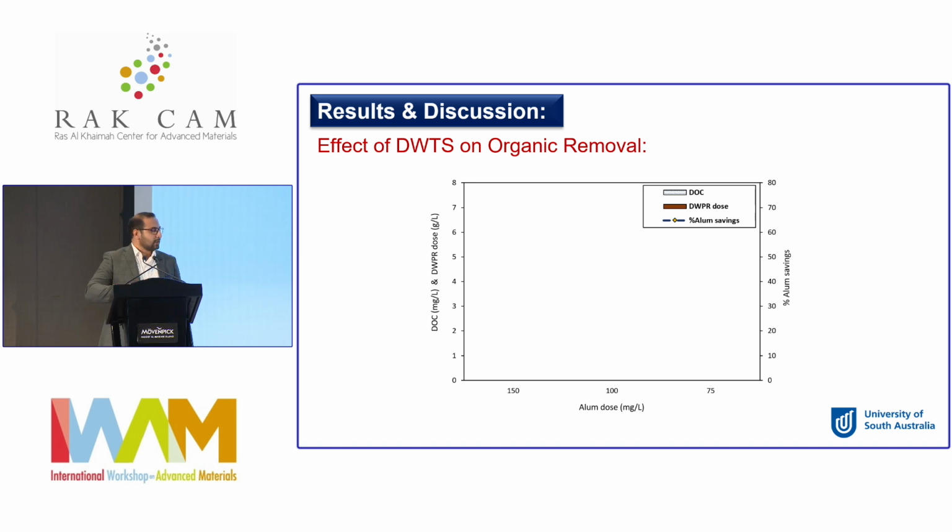So just a brief look at the results we found. First of all, regarding the organics, we found that we can get the same residual dissolved organic carbon, or the same residual organics, as if we use the alum only, the coagulant only, without any addition of the material.